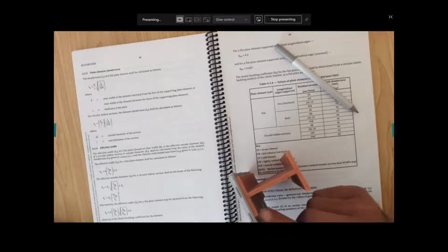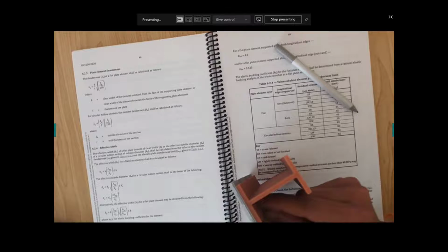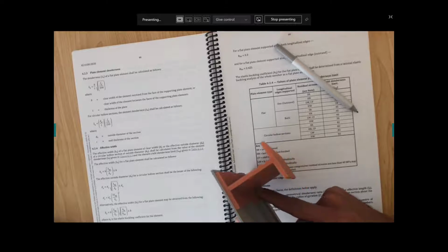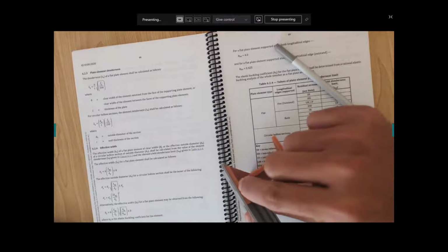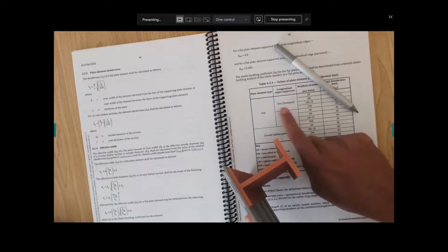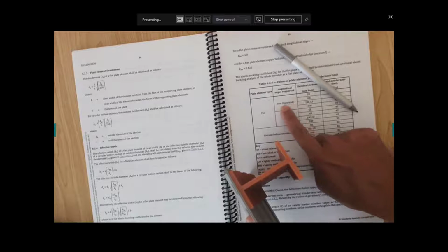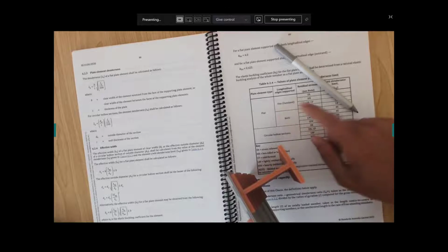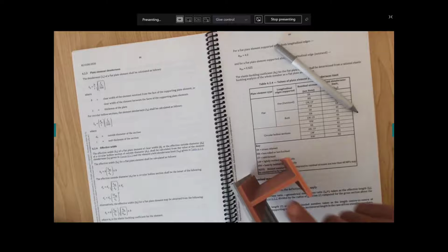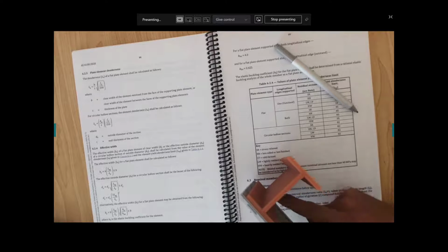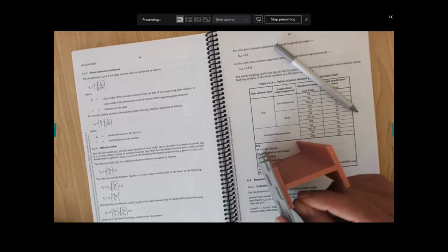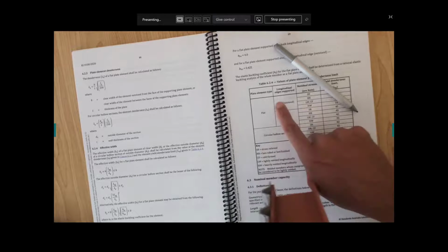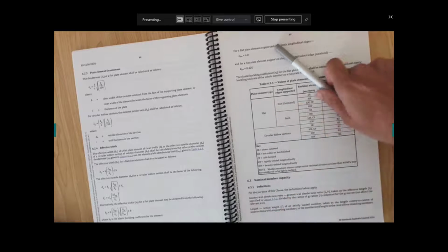There are two longitudinal edges in the flange. One edge is here and the second edge is here. Now one longitudinal edge is supported, one edge is not supported. So we are basically talking about this one for the flange. Basically this is the flange and this is the web. In the web, both longitudinal edges are supported. As you can see, when I load this one, this edge is not supported. So in here, we're going to work with the flange in this particular first line.